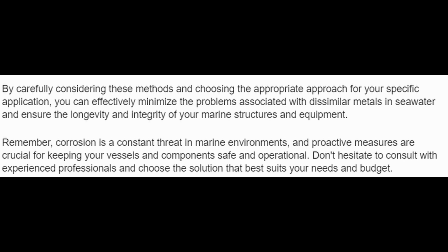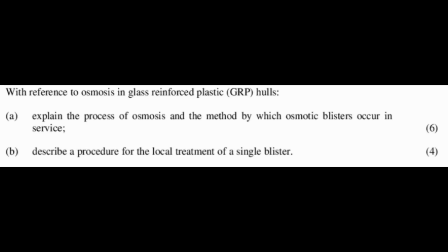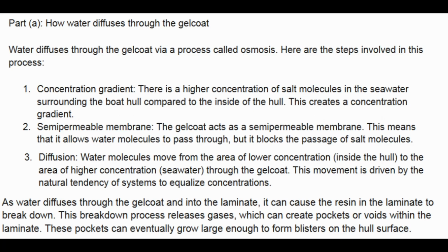With reference to osmosis in glass reinforced plastic GRP hulls. A. Explain the process of osmosis and the method by which osmotic blisters occur in service. B. Describe a procedure for the local treatment of a single blister.